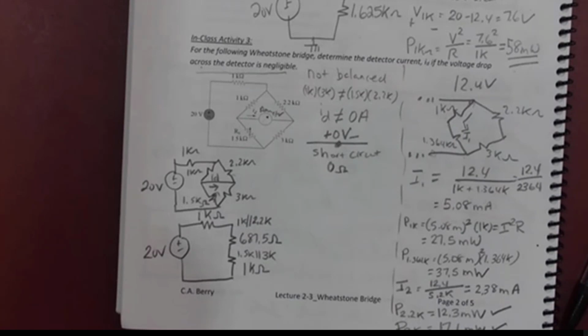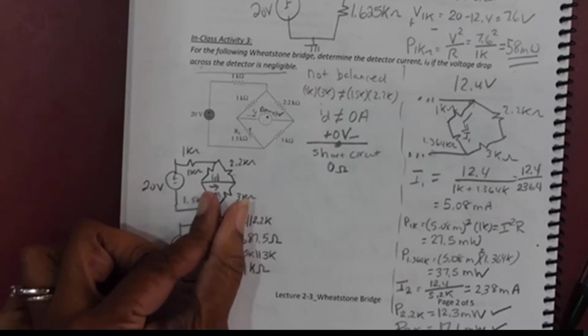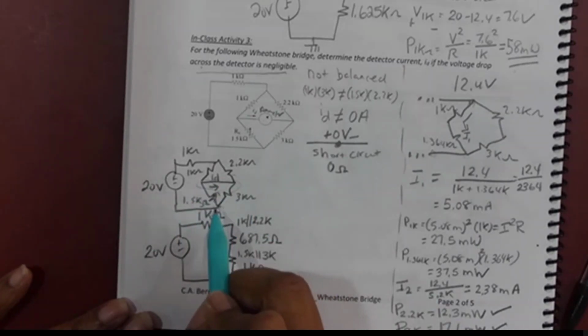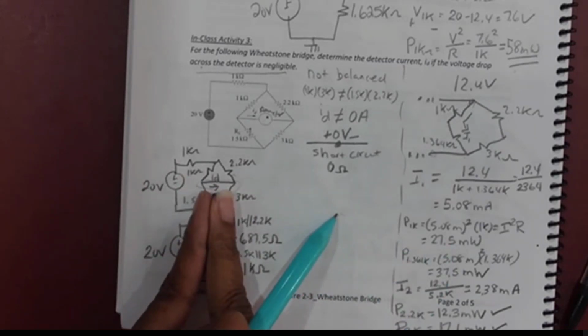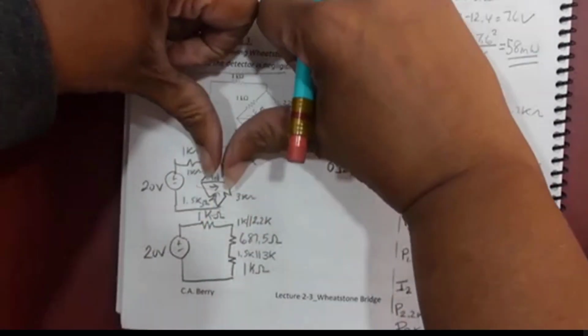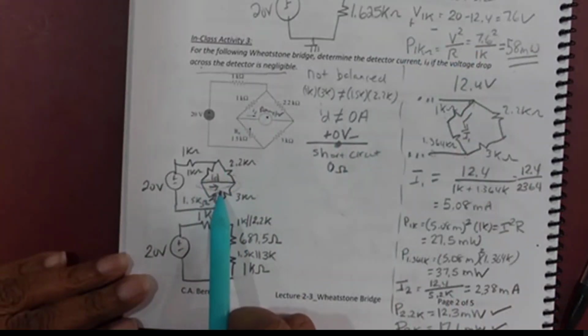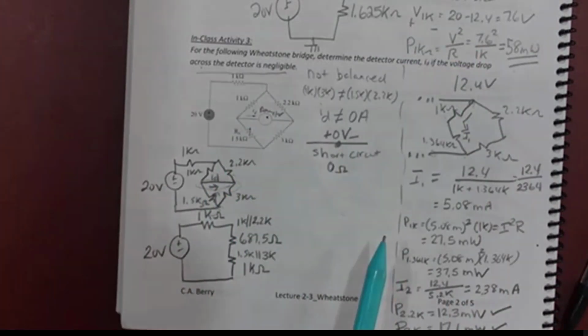Yes, talk to me. After you combine the parallel ones, why do they become series after that? Well, think about it like I'm squeezing these two together, right? So this is all one node, that's all one node. When I put them in parallel, these are squeezed together down here. And when I put these two in parallel, they're squeezed together up there. And since they share that one node, they're in series. Because when two elements meet at a node, they're in series. Okay? Other questions?